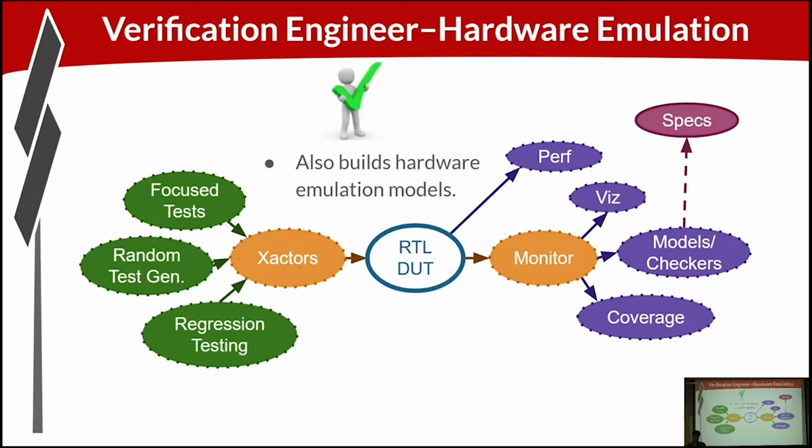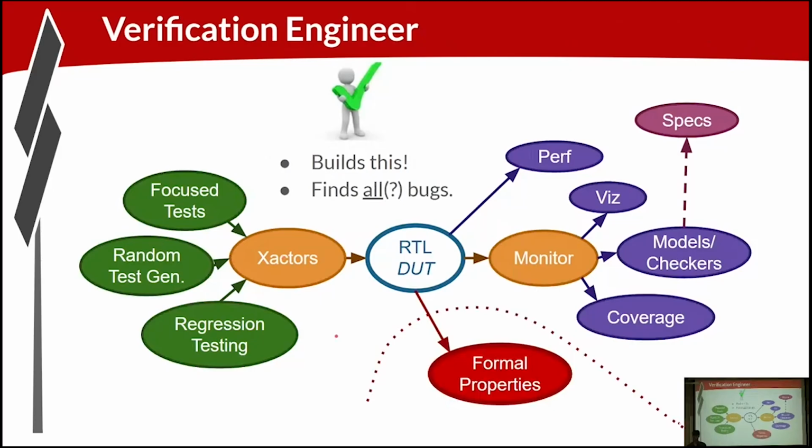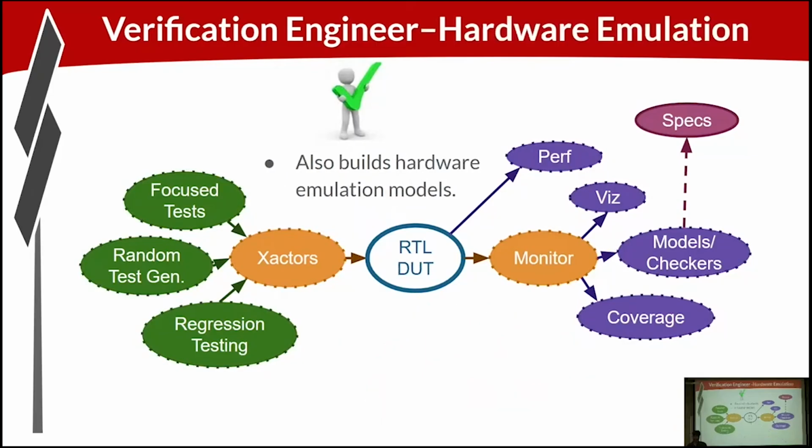And you can't afford to have the same level of software running in that ecosystem as you can in simulation, when your simulation runs are shorter. So there might be considerable work to rework the nature of the transactors and the monitors. There'll be things that you would run when you're running simulation that you would disable for hardware emulation.